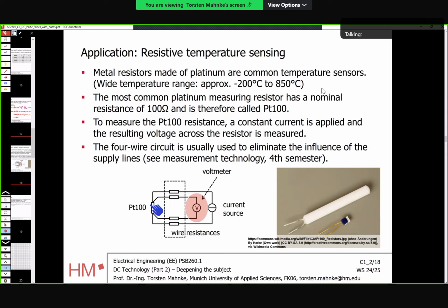You take the wires out, apply a current source or a voltage source. You will see a current flowing. You can measure the voltage, you can measure the current, you can calculate the resistance. When the temperature within the chamber changes, of course, current and/or voltage will change, and you calculate a different value for the resistance. Then you can use the equation that we just used here and solve it for the temperature theta. On the left side of the equation, the resistance will be known from the measurements. You solve it for theta and calculate the temperature.